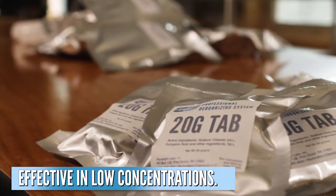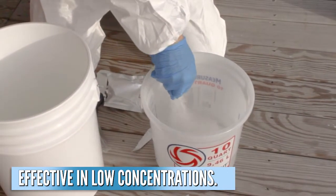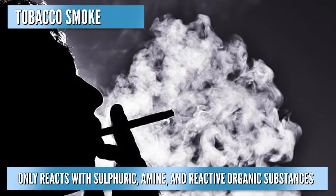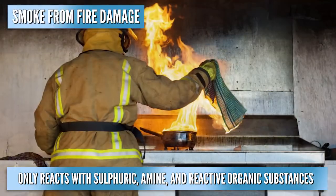Chlorine dioxide has been used for the past 200 years for the purposes of disinfection, odor control, and odor elimination. Because it's a strong oxidizer that is both selective and non-reactive, chlorine dioxide is effective in low concentrations. It only attacks organic molecules with electron-rich centers, and it only reacts with sulfuric substances, amines, and reactive organic substances.